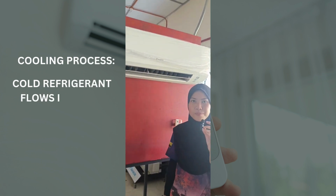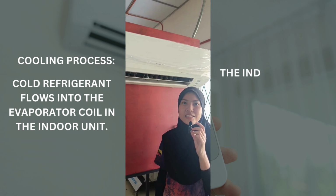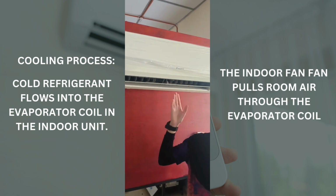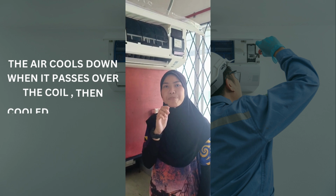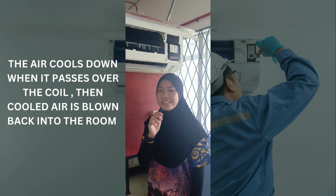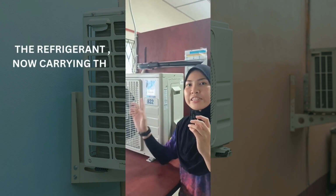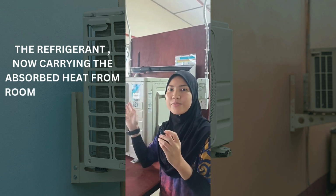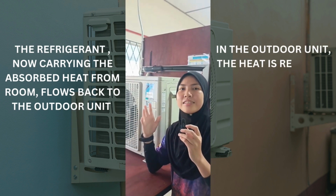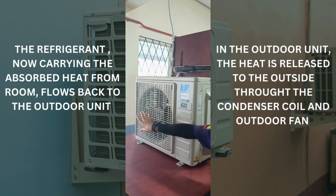Next, cooling process. Cool refrigerant flows into the evaporator coil in the indoor unit. The indoor fan blows room air over the evaporator coil. The air cools down when it passes over the coil. Then the cool air is blown back into the room. Next, heat rejection. The refrigerant, now carrying the absorbed heat from the room, flows back to the outdoor unit. In the outdoor unit, the heat is released to the outside through the condenser coil and the outdoor fans.